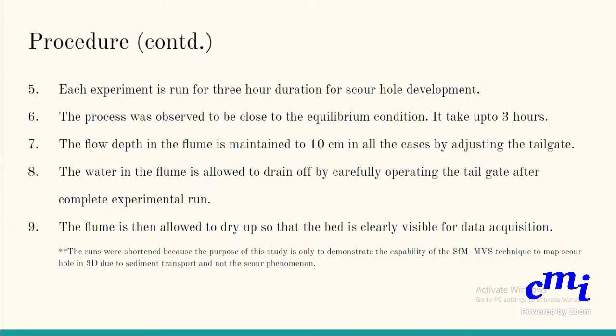Yeah, each experiment ran for a 3 hour duration for the scour hole development, and the process was observed to be close to the equilibrium condition. It takes up to 3 hours, and the flow depth is maintained at 10 centimeters in all cases, done by adjusting the tailgate. And after the experiment is done, they allowed it to drain off the